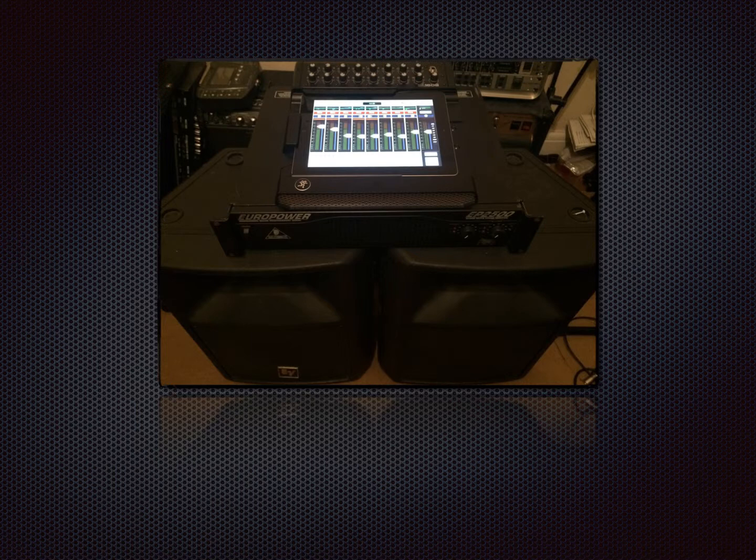An important factor here is that the power output of the amplifier matches the power handling capability of the speakers. The speakers are the component which convert the signal sent from the power amplifier into sound. Different sound frequencies need different size speakers to project the sound correctly, which is why these speaker cabinets have two different size speakers, a small high frequency speaker and a larger speaker for the low and mid frequencies. They also have what's known as a crossover built in. The crossover splits the frequencies and directs the signals to the correct speakers.